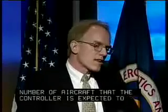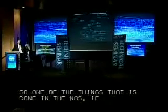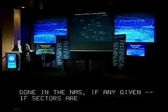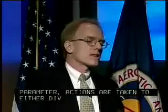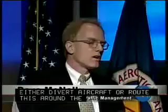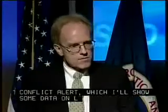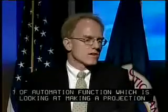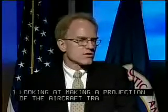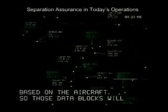So one of the things that is done in the NAS, if sectors are predicted to go over their monitor alert parameter, is that actions are taken to either divert aircraft or route them around the sectors. Let me just say a bit about some automation available. Conflict alert, which I'll show some data on later, is a legacy automation function that makes a projection of the aircraft trajectory based on 2 or 3 track hits. So if any of those aircraft are predicted to lose separation within 2 or 3 minutes, those data blocks will start flashing, alerting the controller to the potential problem.